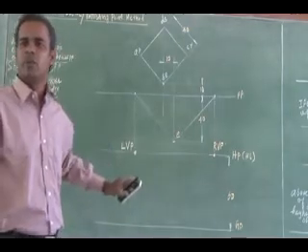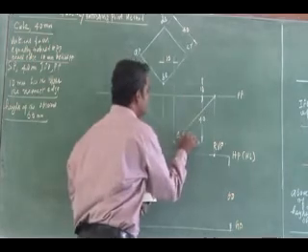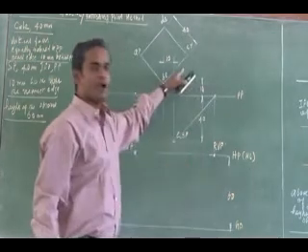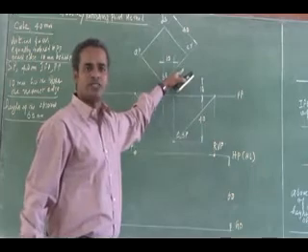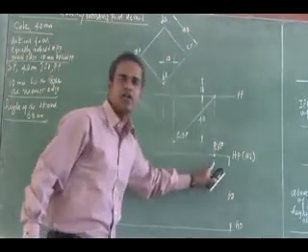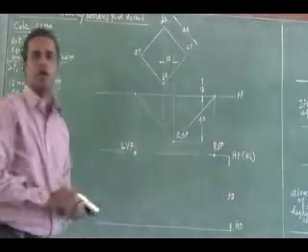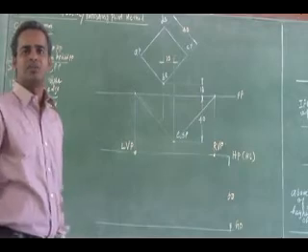So obtaining a vanishing point: draw parallel lines from the station point to one parallel face and one inclined face. I will obtain it on the picture plane by dropping that to the horizontal line. I will obtain the right vanishing point. Similarly, the left vanishing point I have got. Now to get the perspective.